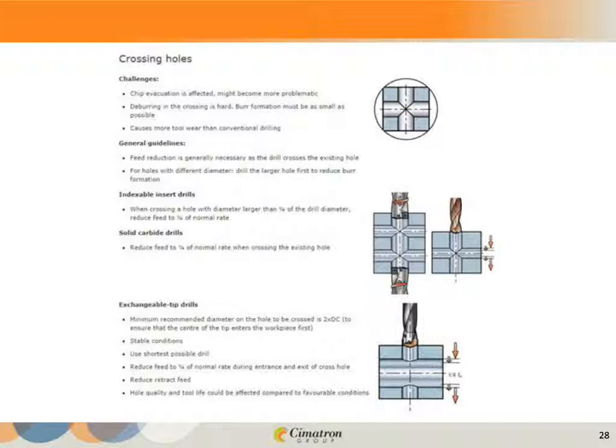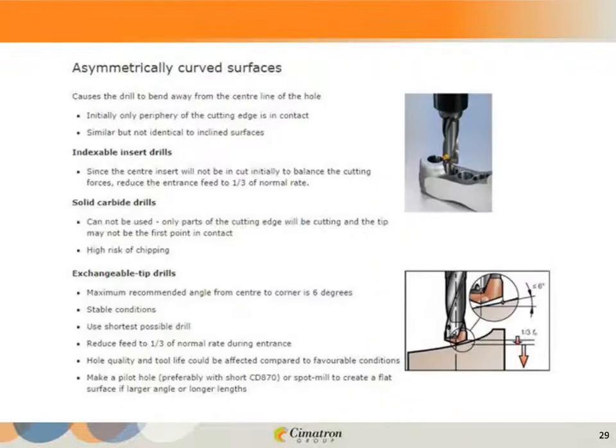And here, of course, if you're trying to drill on an asymmetrical surface, it's going to require machining like we discussed earlier. Although I think in this picture it's showing that if the angle is enough to not obstruct the flute and the drill is stubby enough, you can probably get away with a situation like this. Again, it's very specific to the application.